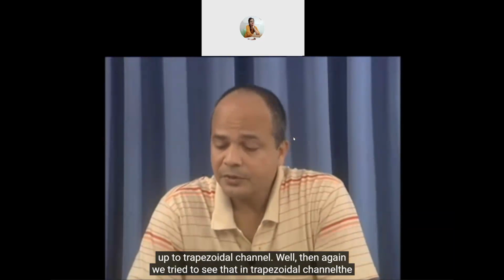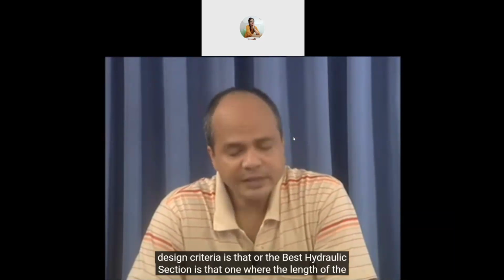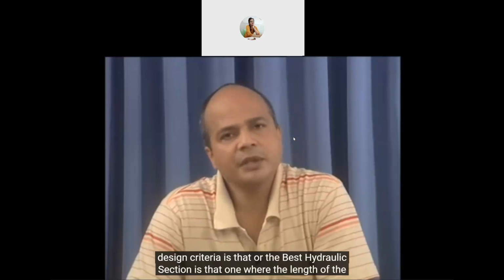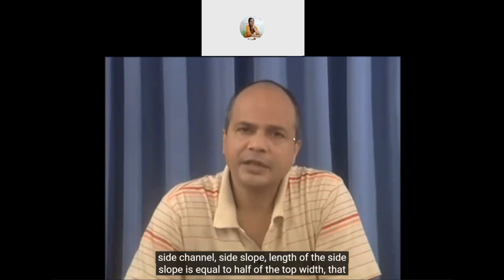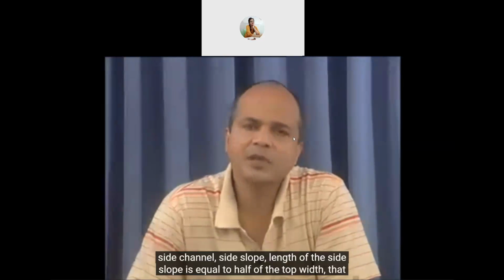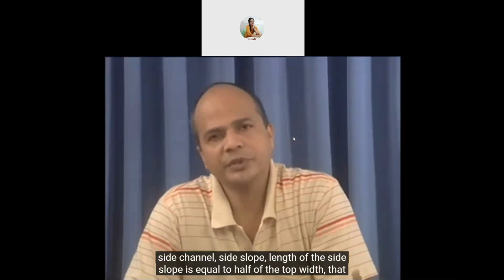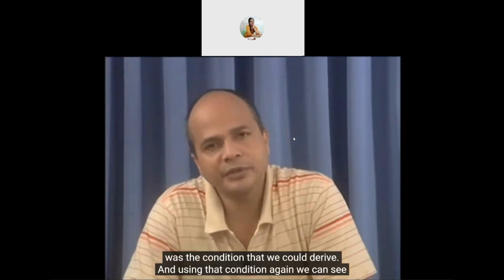Then again we tried to see that in a trapezoidal channel the design criterion for the best hydraulic section is the one where the length of the side slope is equal to half of the top width. That was the condition that we could derive.